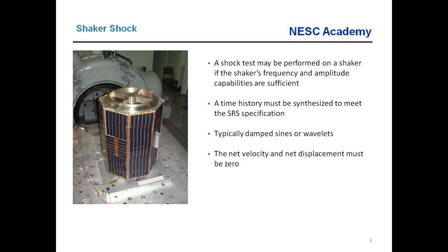And I'm going to say that the net displacement must also be 0. Well, in reality, we could tolerate a slight net displacement as long as the shaker table could recenter itself thereafter. But just for simplicity, let's say that the net velocity and net displacement must each be 0. So that's the requirement for our time history synthesis, regardless of what type of waveforms we use.